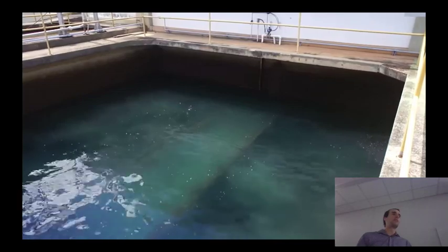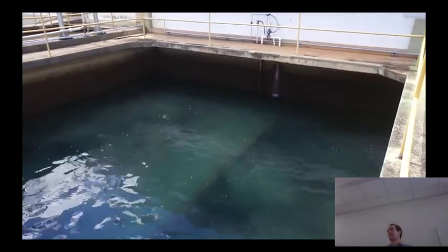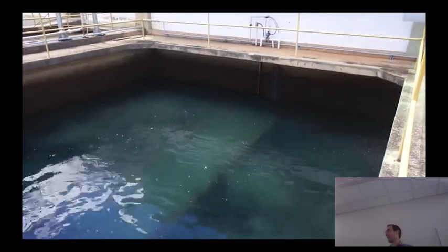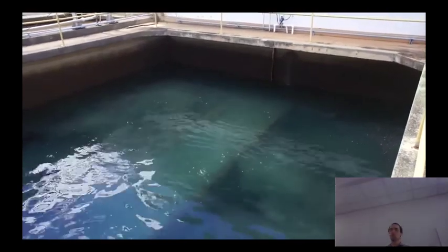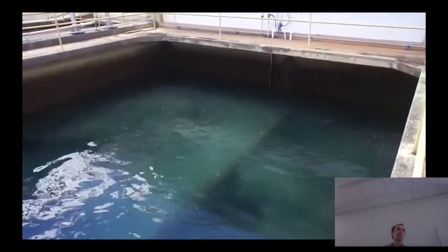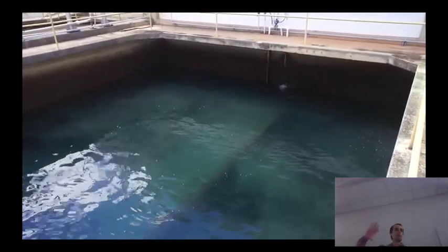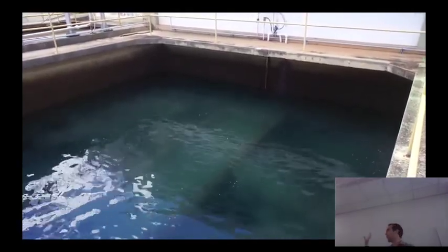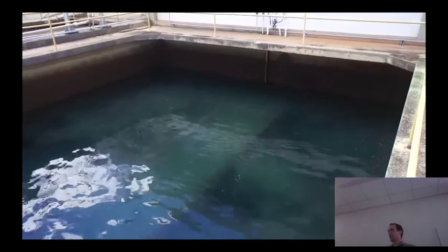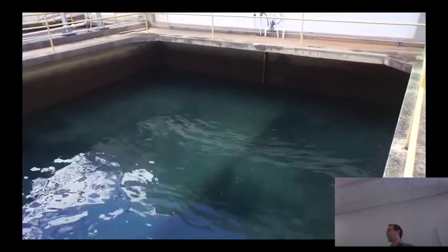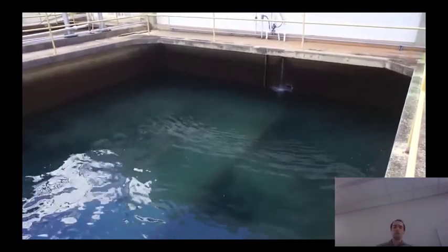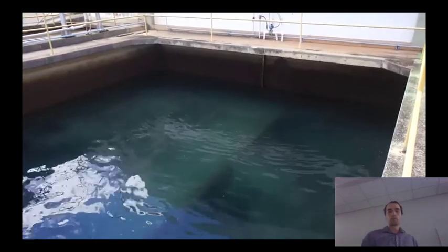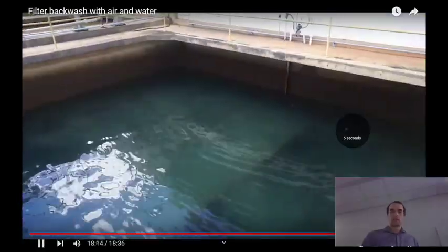As you can see, it wasn't an exact science of getting every last particle out of this water, right? So there are probably still some particles in and around. It makes sense then that we take the first 15 minutes or so of water produced by this now and send that to wastewater as well, right? It's an important feature of the system to get it working properly.